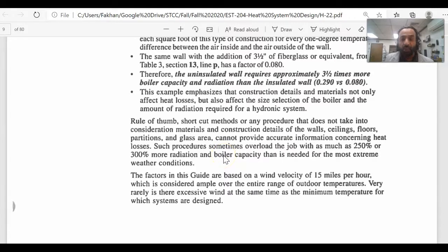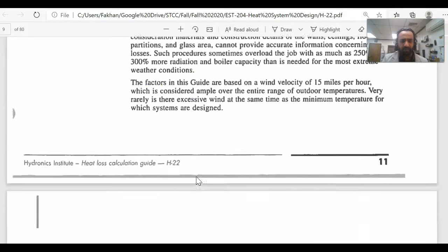They're not necessarily what is actually existing on the wall. So it will be very beneficial to go and examine the wall yourself and see how thick it is, do some measurement, what's inside the wall, what's the siding, what is in the inside. Sometimes even wallpaper does make a difference. So that's something you have to consider a little bit in the heat loss.